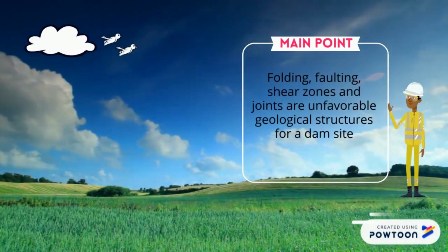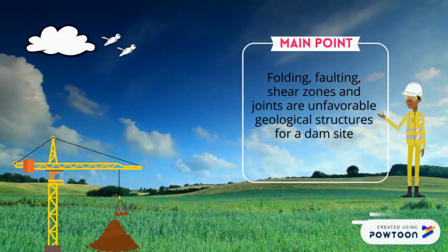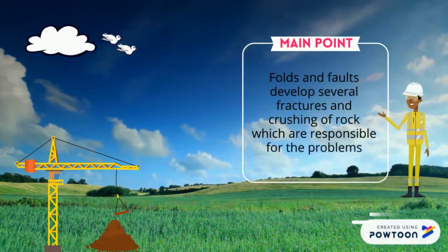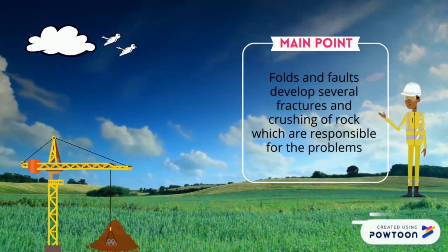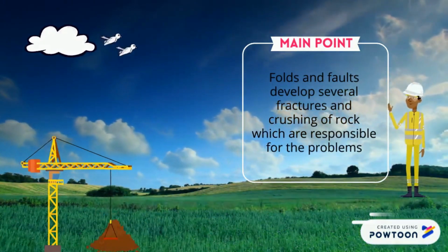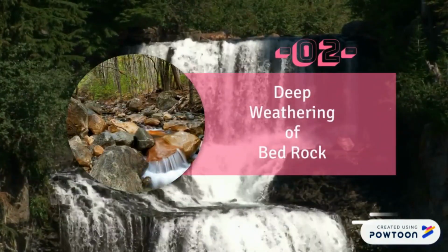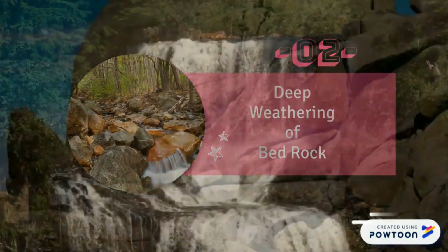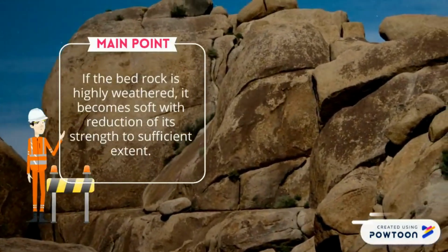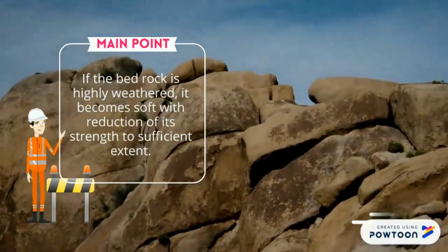Folding, faulting, shear zones and joints are unfavorable geological structures for a dam site. Folds and faults develop several fractures and crushing of rock which are responsible for the problems. If the bedrock is highly weathered, it becomes soft with reduction of its strength to a sufficient extent.